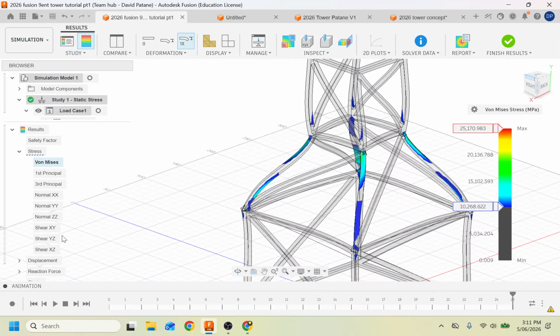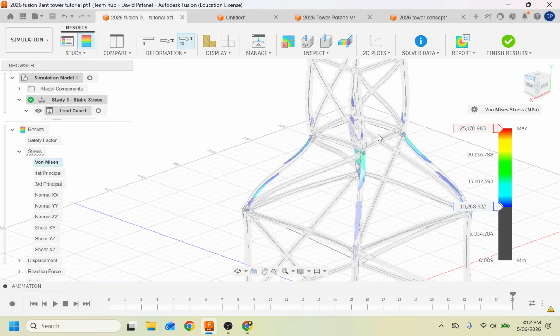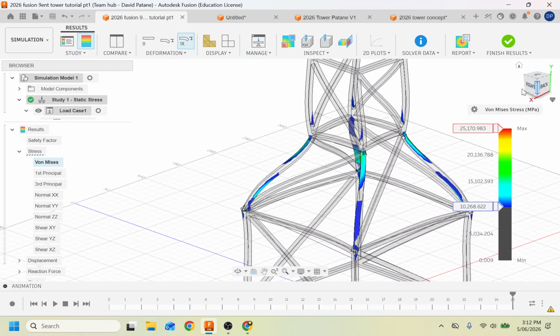We can make it thicker. Yeah. Oh, we can add another member here, a diagonal or another horizontal member, to reduce that length. Again, we're using more material if we do that, or we can double the thickness. We can change our I value as well. We can put two pieces of balsa wood on top of each other if it fits in our design. But that's where the most stress is, so that's where it's worth putting it.